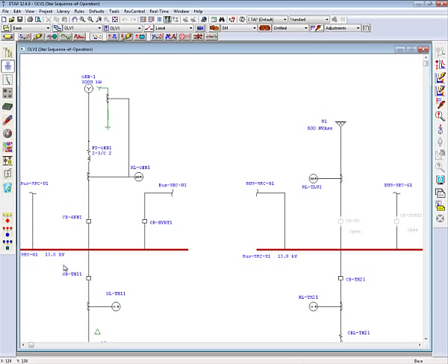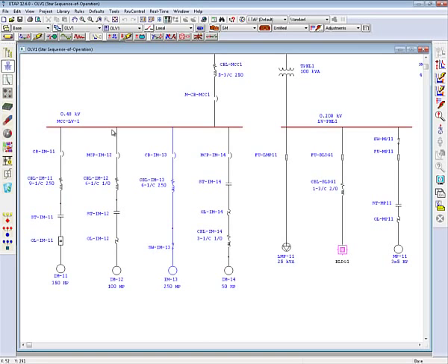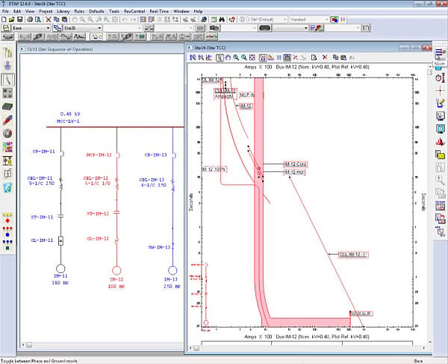So what we are going to do is try to set up one protection scheme. We're going to see how we can protect our motors. Let's for example take motor IM12. If I select the motor, rubber band all of the equipment protecting this motor and create a Star view, I can see the time current curve, or Star view, of the protective devices and the element which needs to be protected.